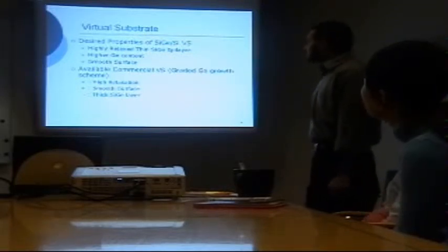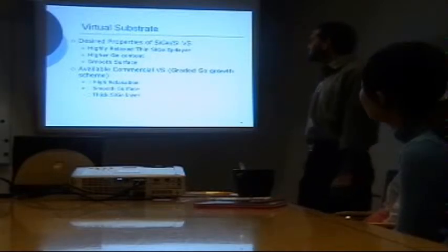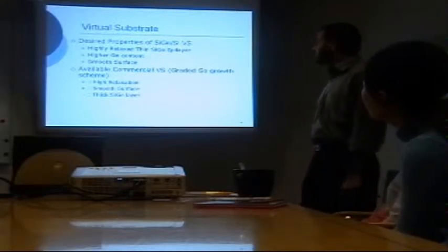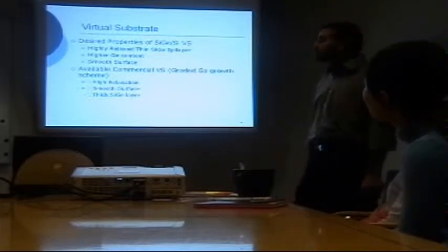So what should be the desired properties of these silicon germanium virtual substrates? They should have a highly relaxed thin silicon germanium epilayer. They should have higher germanium content and a very smooth surface.